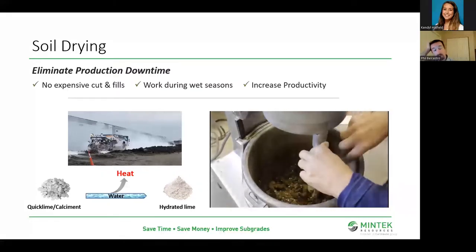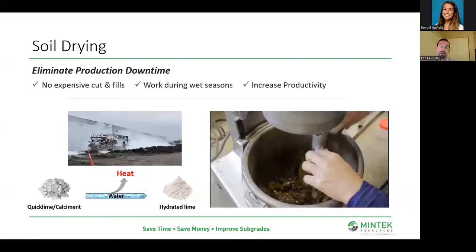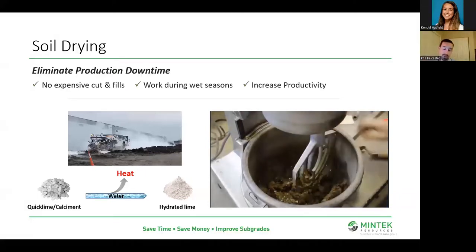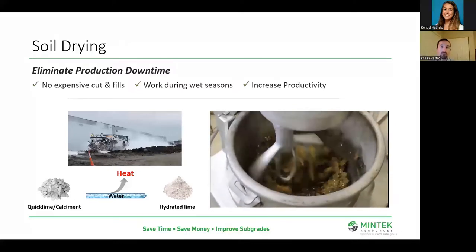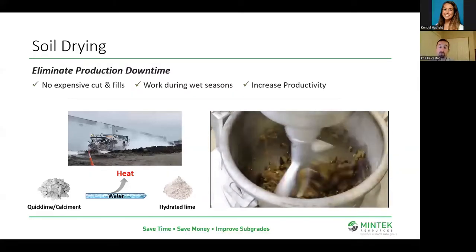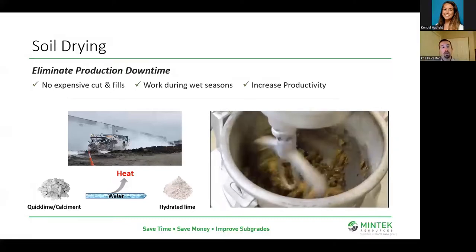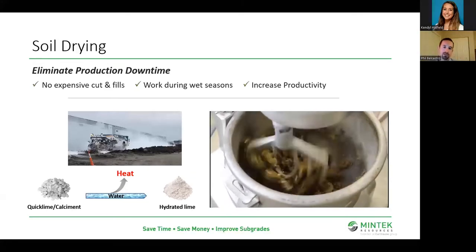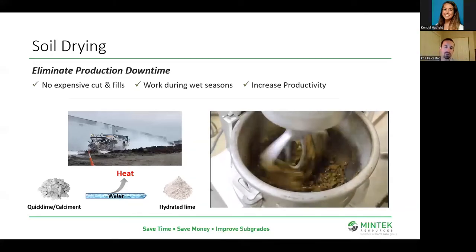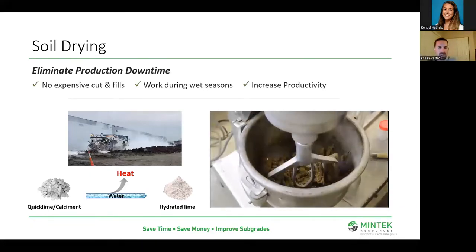Like I said, very exothermic reaction. We have an example where we actually fry an egg, using just lime and water. The right, or maybe wrong, proportions of lime to water can generate some really impressive heat. As I've been talking on the slide for a minute and a half to two minutes here, we can already see that that soil is getting much more friable, much more workable. We can see some of the action happening in that bowl.